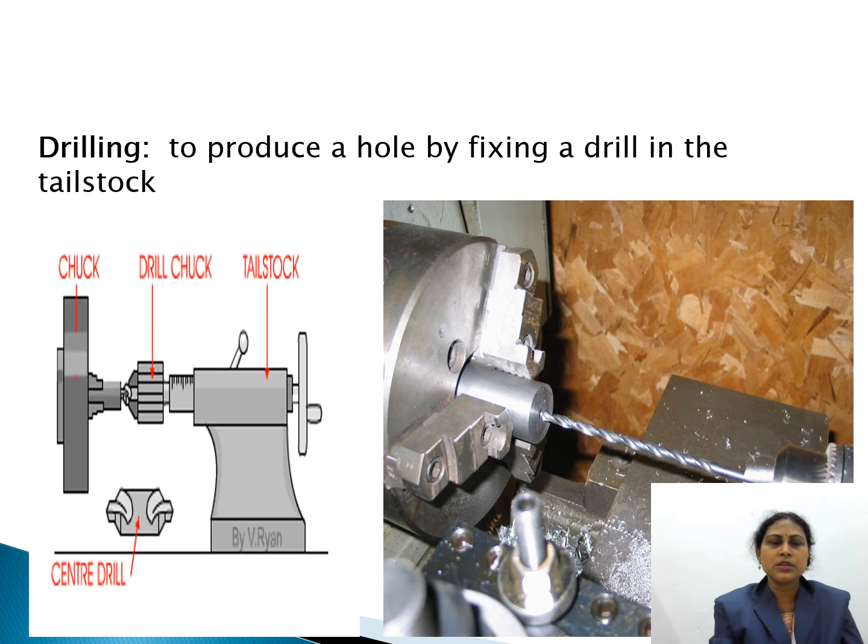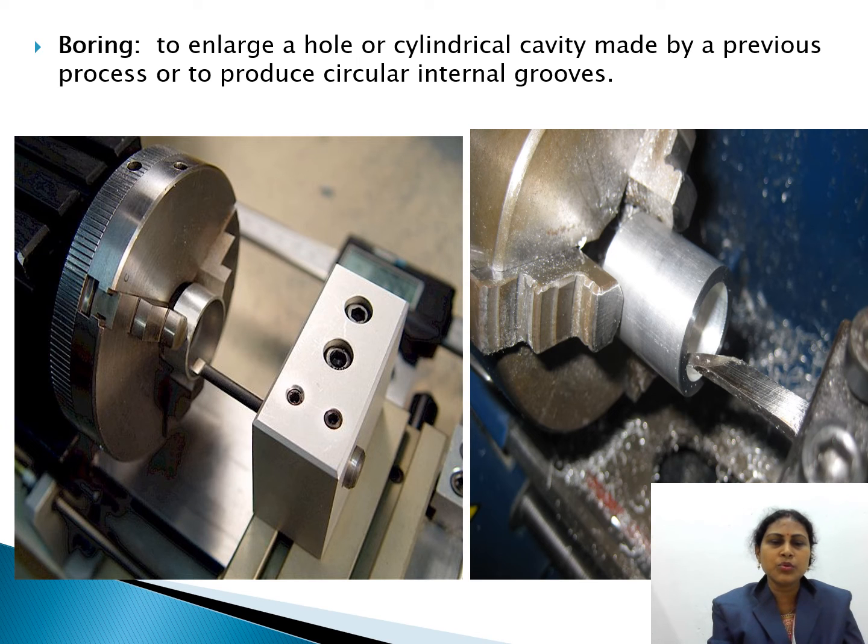Then drilling. Drilling means to produce a hole by fixing a drill in the tailstock. Boring. Boring enlarges a hole or cylindrical cavity made by a previous process, or produces circular internal grooves.